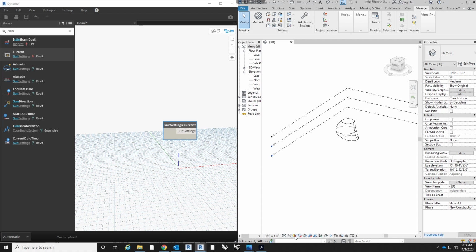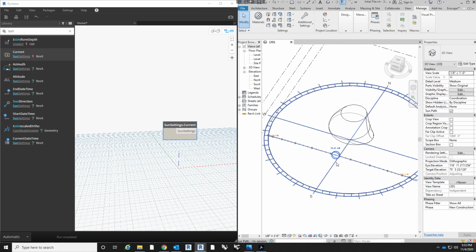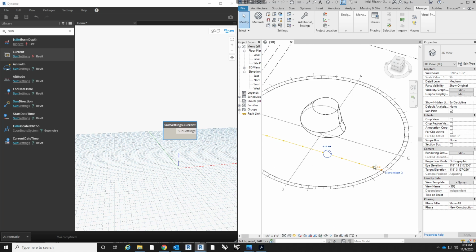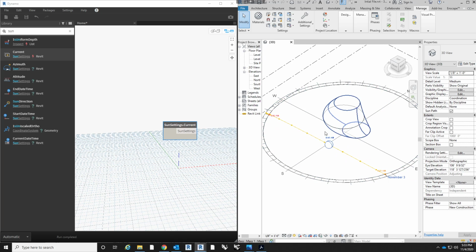down at the bottom left, and I think you've probably done this before, there's a little sun path, sun icon, and this can turn on and off the sun path. So you can visualize the sun path in Revit by just selecting this on. And this little ball up here actually tells us where in the sky the sun is. Now, some of you probably aren't seeing this, so I want to get into how to actually get that sun and get the different positionings of the solar orientation.